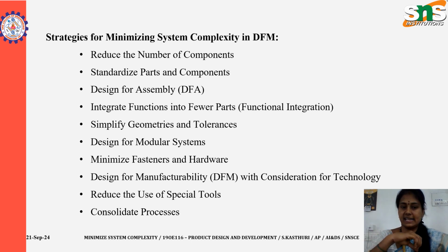Next one is design for modular systems. Create products with modular sub-assemblies that can be easily swapped, tested, or replaced. Minimize fasteners and hardware. Reduce the number of fasteners like screws, bolts, and nuts, or eliminate them entirely by designing parts that can interlock, snap, or be welded.